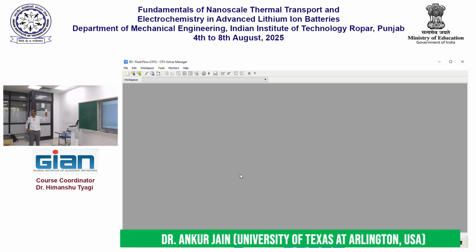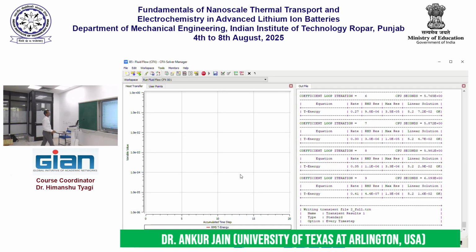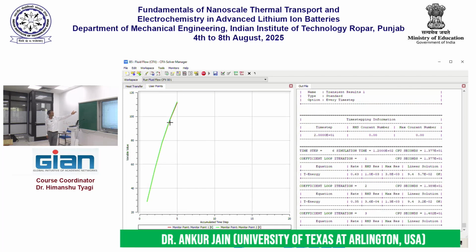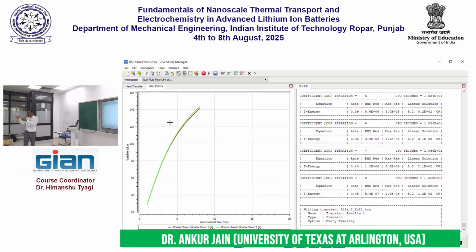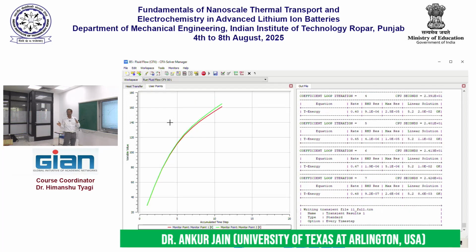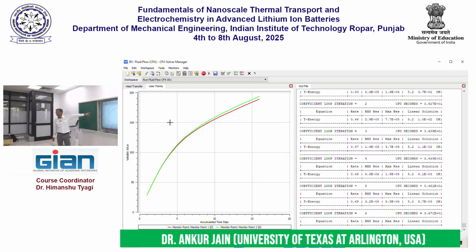This is where it is setting up those equations, creating the matrix, doing the matrix inversion sometime now, and solving for temperature. These are my user points. The two cells have roughly the same temperature. One of them is slightly hotter because it was farther away from the heating boundary. You know, if it had been completely symmetric, these two curves would have been exactly identical to each other. And as you can see, it rises very fast to begin with and it slowly stabilizes.